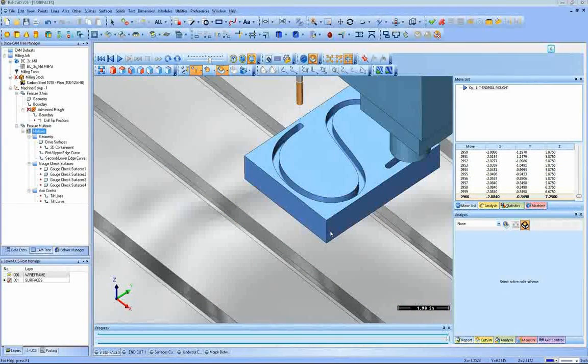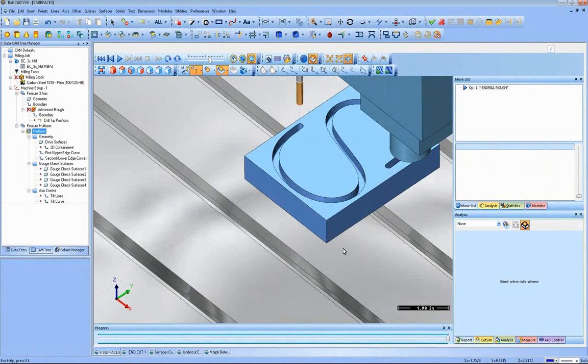You know, if you have a tool that's maybe the shape of the channel, a lot of people want to walk that tool just down the center line. That's the perfect toolpath to be able to do that. And you can use your own ground up tapered flat bottom tool for that. Okay, so I'm going to close the simulation.